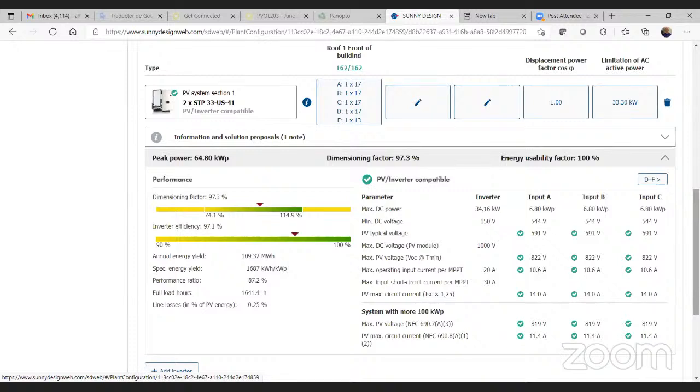So if it is a really high power or high current module with high backside gain expected, it may be best to have only one string of modules per each of the 6 input channels. But generally the STC rating of those modules is also, in terms of power, much higher, and 6 strings staying under 1000 volts might still provide a good range of choices for good DC to AC loading ratios.